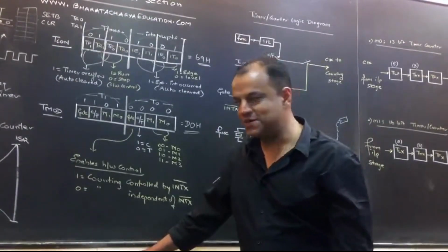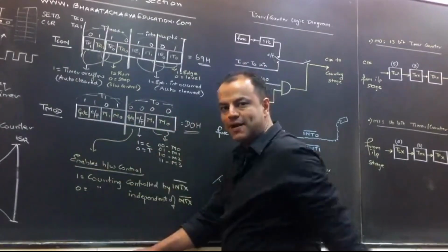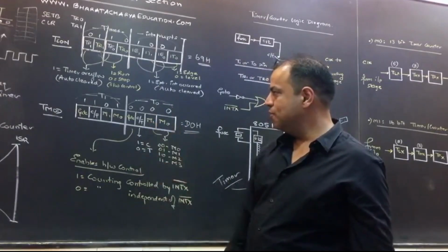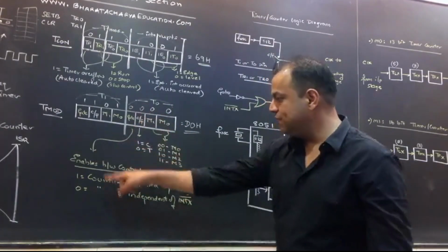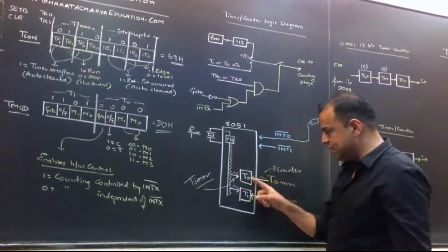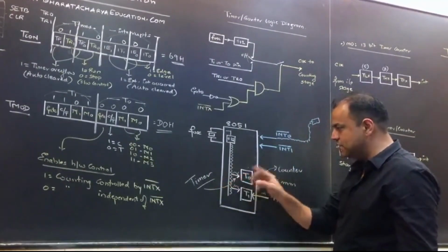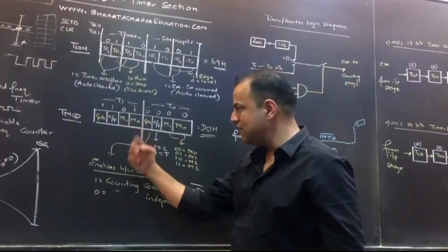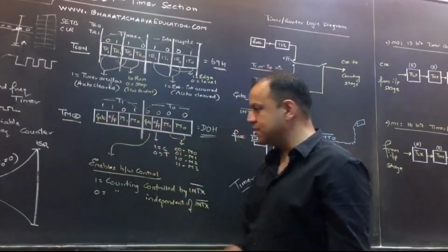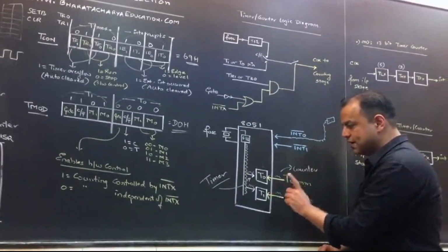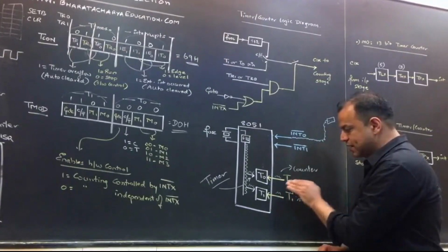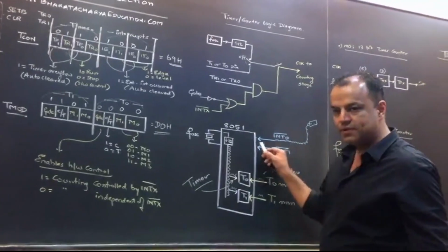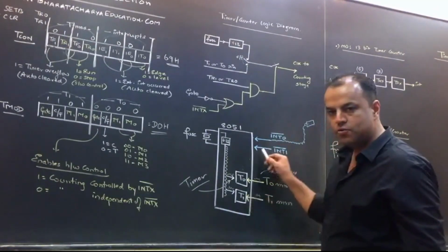This is again a 5-mark question. Draw TMOD, draw the binary pattern of D0 and start. Timer 0, working in mode 0, working as a timer, and we don't have any hardware control feature. Timer 1, working in mode 1, working as a counter, that means it will take external clock, and has hardware control. Has hardware control means INT1 will control timer 1 internally.